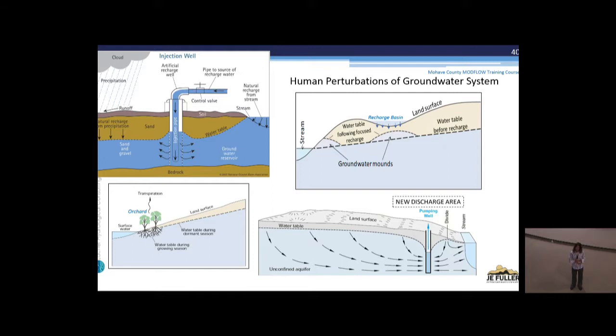That's an excellent question. It really, really depends. If you're in Avra Valley in southern Arizona, it could be 300 feet to groundwater. So the more consistent you are with your inputs, the more you're going to set up a flux, a continuous flux, which is going to happen much more quickly. It's going to make that mound build quickly. The wetter the soil is, the more quickly water transmits through it. The drier it is, the worse it transmits.